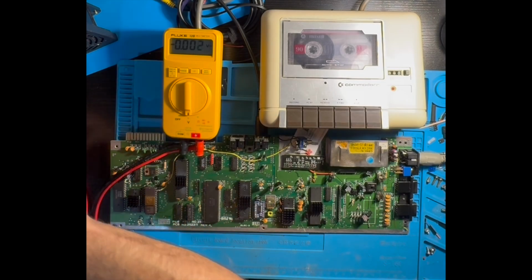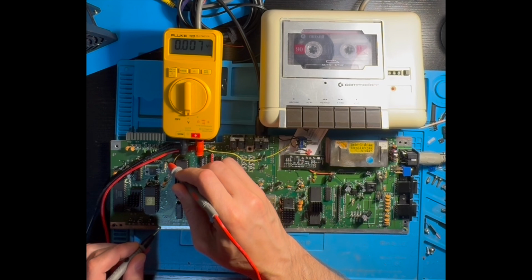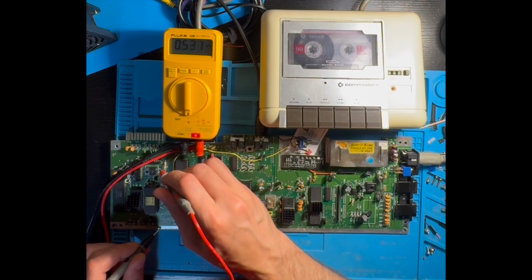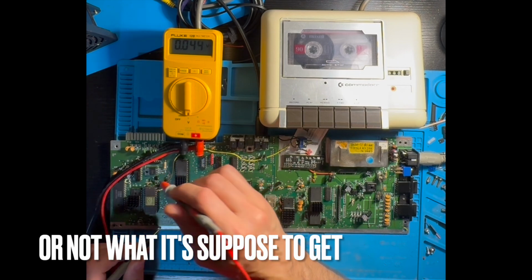And then I flipped over to the other side, the left side of the schematic, near the cassette port at the top. And I'm looking at resistor 1, R1, is where that 9 volts unregulated is coming to. So then I thought, well, let me check the continuity between those two points and look for voltage coming out of them. So I pulled the board out and I'm checking voltage, and I can see R1 right there. It's not getting any voltage. And I'm like, okay, well, that's a problem right there.